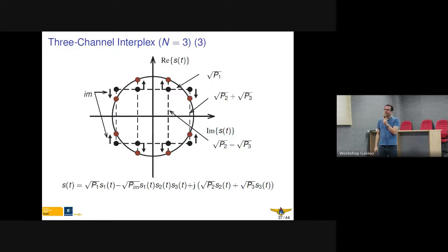Okay. Thank you. On the other hand, you could in the receiver also use, and this is also for the interplex, a replica building exactly this signal, and then demodulate the complete signal. In many cases, this is not possible for the user because one of the components is a cryptographic signal. So for the non-military user, it is not possible to demodulate the complete signal on the carrier. That's why they stick to correlating with only one component or two components in the receiver.